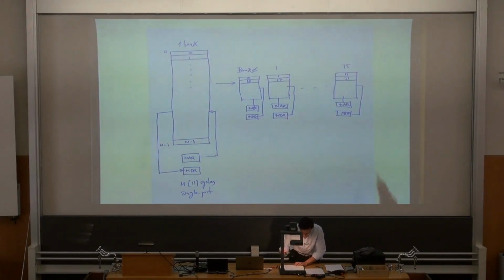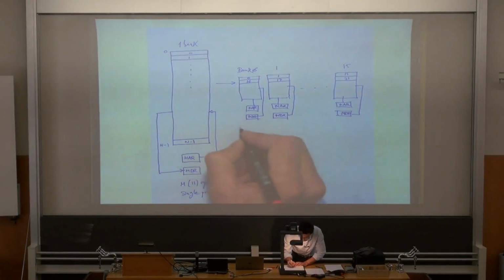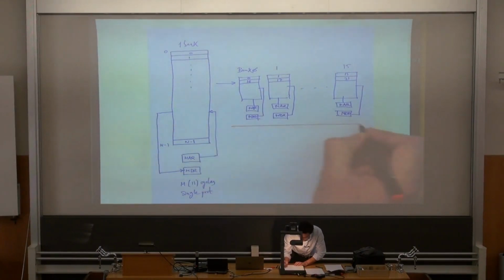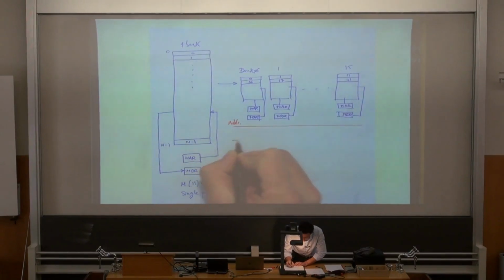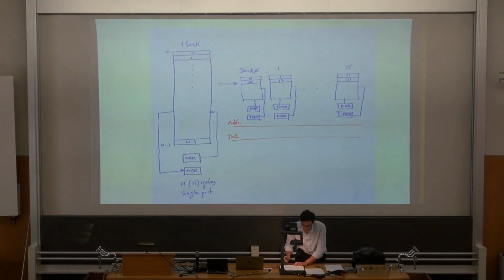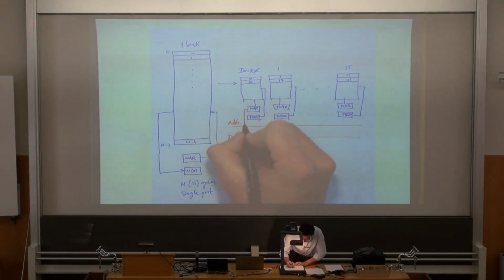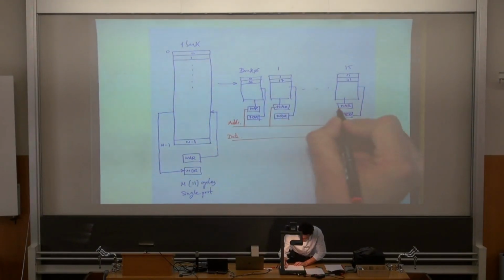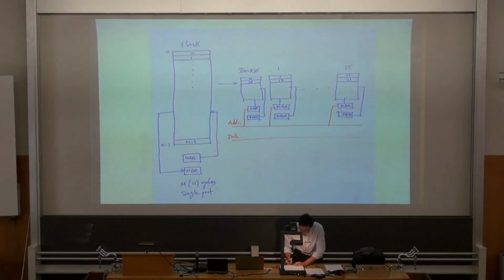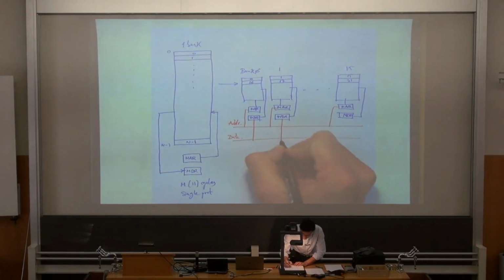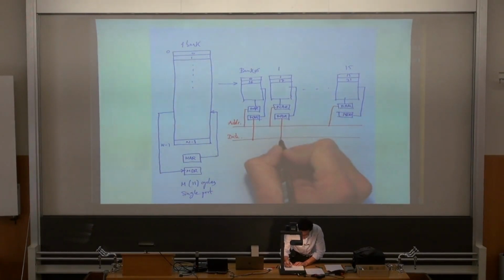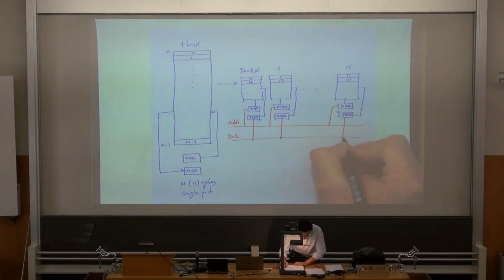All these banks share the same address and data buses. So memory address registers are connected to the address bus. Memory data registers are connected to the data bus.